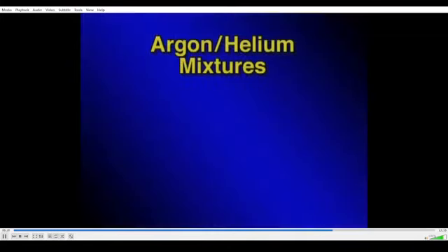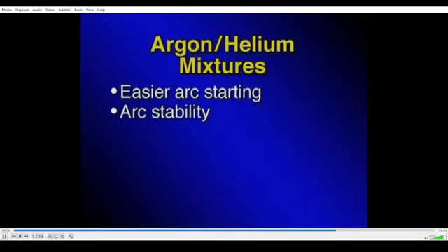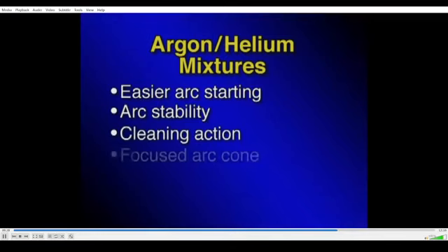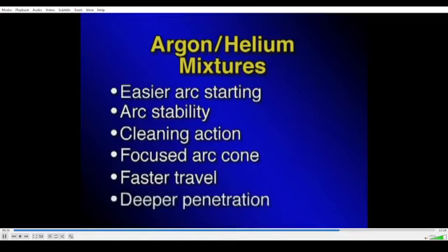Argon and helium are often mixed to take advantage of the best that both gases have to offer, like easier arc starting, better arc stability and cleaning action, a more focused arc cone, faster travel speeds, and deeper penetration.